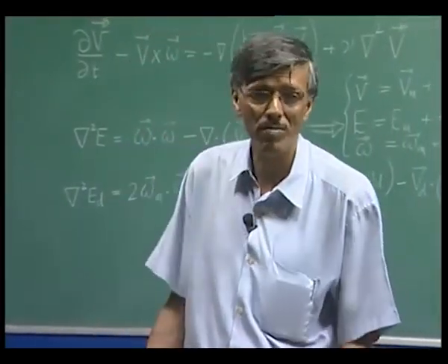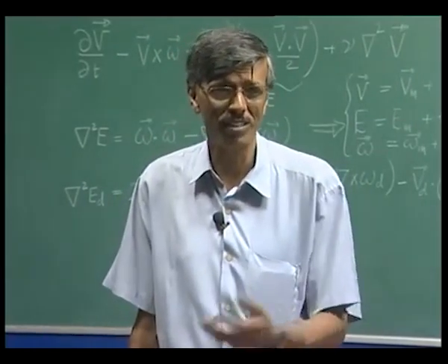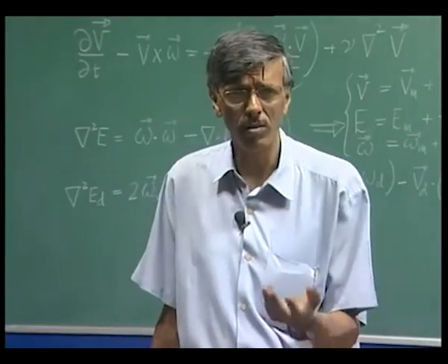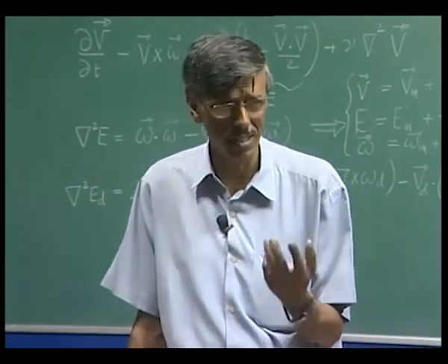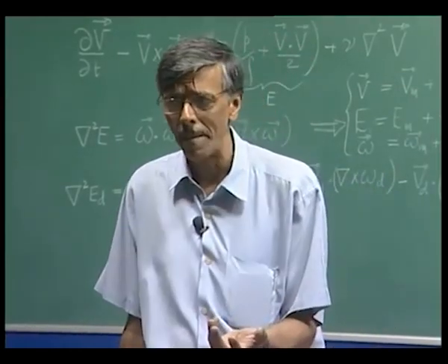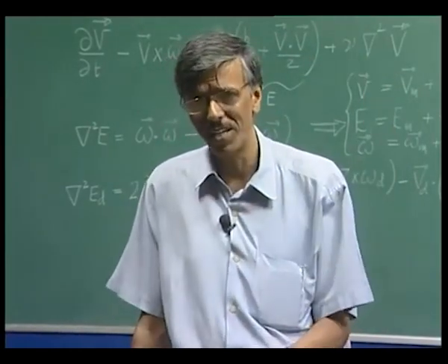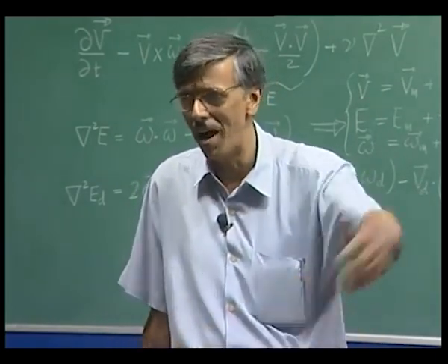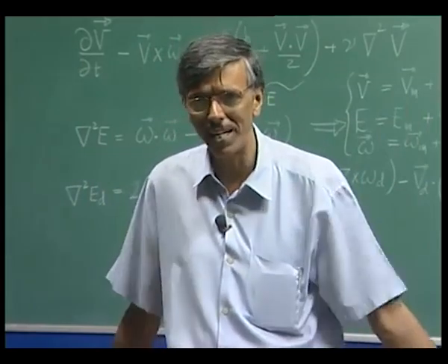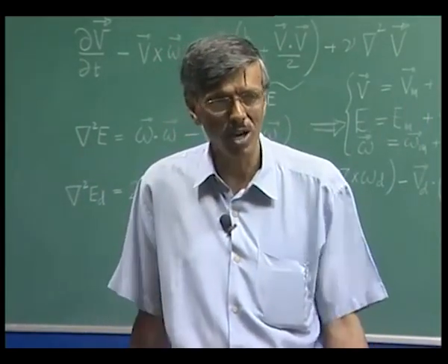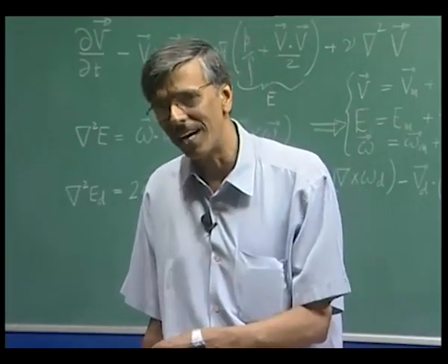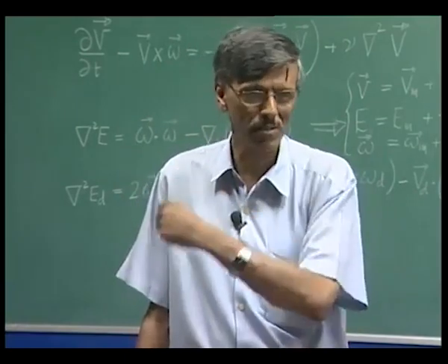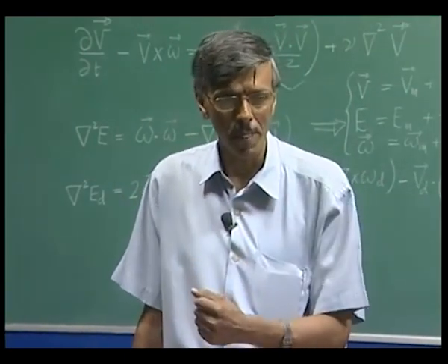Now, Tollmien-Schlichting wave seeing is what? If you recall the Schubauer-Klebanoff experiment, they did excite the system with a single monochromatic frequency, right? Single frequency. So, a monochromatic disturbance field. But if I put a rivet on an aircraft wing, then what is the frequency? Say I have free stream turbulence coming, that has embedded in it a frequency spectrum, not a single frequency. So, as a result, for each frequency, I am going to get a wave number if my dispersion relation is correct.